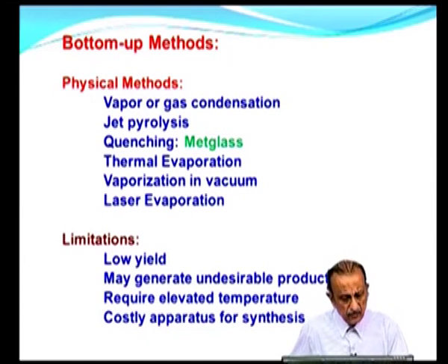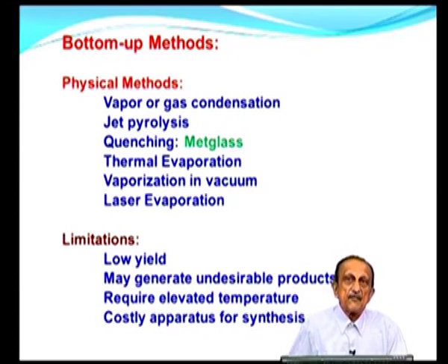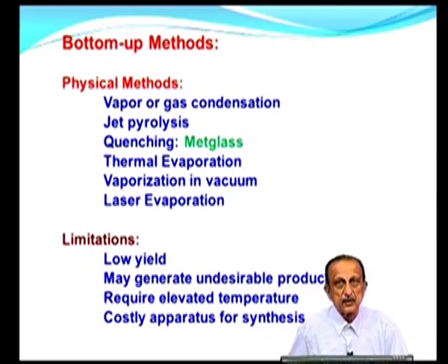Thermal evaporation. We have discussed evaporation and condensation. Again, thermal evaporation of, let us say, metals or metal oxides or some such material in a vacuum system, which is often the way to produce thin films of these materials. Suppose you collect these evaporants, including metals, on a cold substrate. Normally, this is done on a substrate that is at room temperature. In a high vacuum, one evaporates material and collects it on a substrate often held at room temperature.